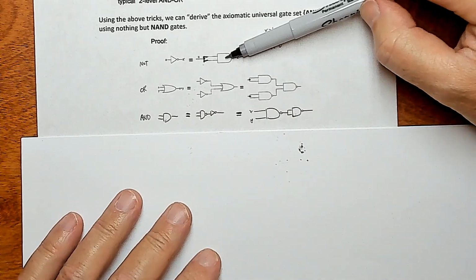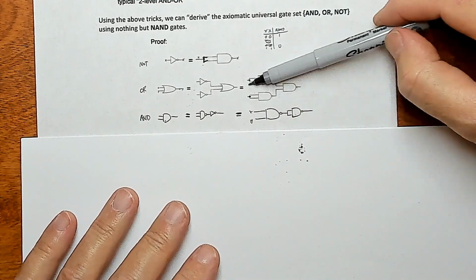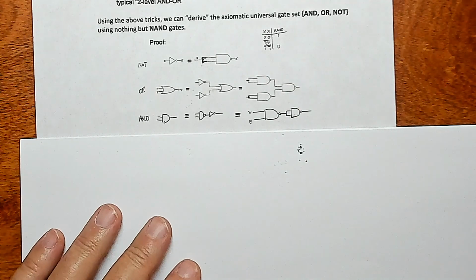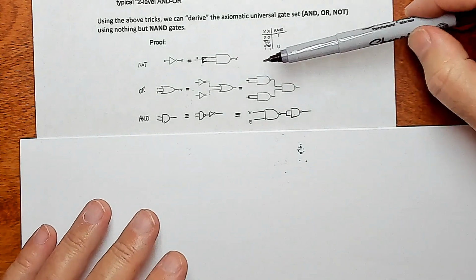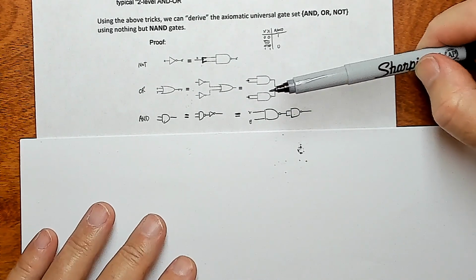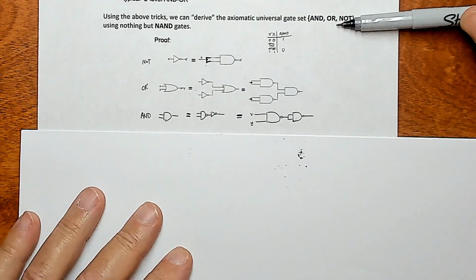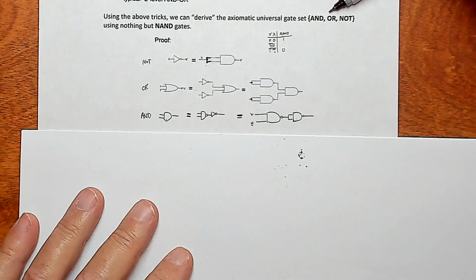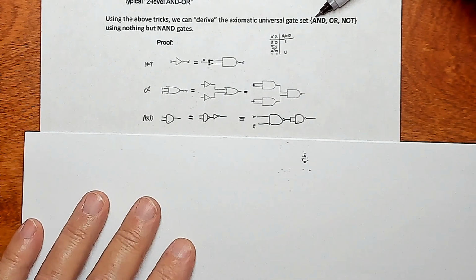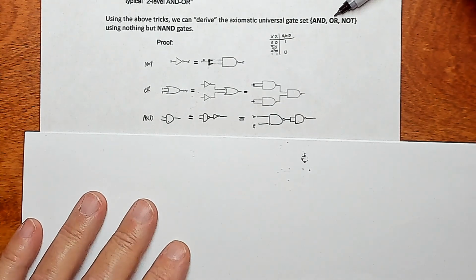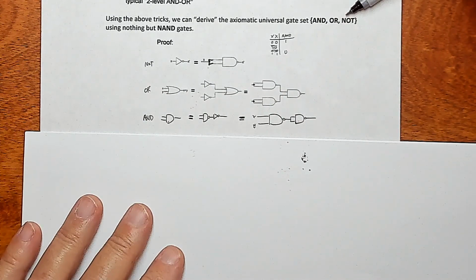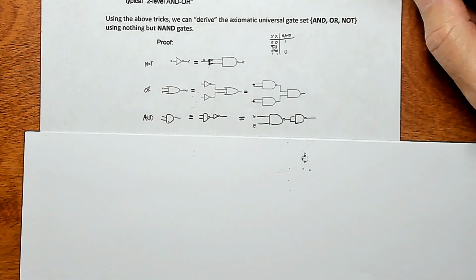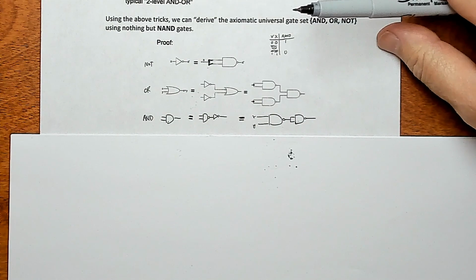It takes more gates, but those gates are small, and you can build a device that is just a giant array of NANDs. The other advantage of just using an array of NANDs is, let's say you made a device that had, I don't know, a third of this and a third of these and a third of these. What happens when you run out of AND gates? Then you've got OR. You might have unused OR and NOT gates. They're just taking up space. But if you use nothing but NANDs, you can fill up the chip with at least something, and that can be a more efficient way to do it.